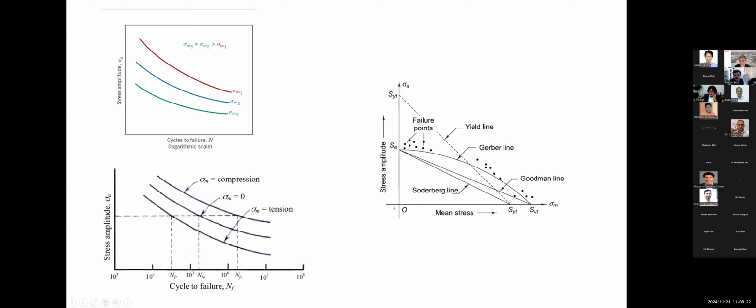So if you talk about no stress amplitude at all, the material will fail here at yielding, or if you take ultimate failure, it will fail here. But in between, what you have are the various yield criteria. We have the Soderberg line, the Goodman line, and the Gerber parabola. It's not a line, actually, it shall be a parabola here. And this is the basic reasoning for drawing the CLDs. That is where the CLDs come from, what we call constant life diagrams.